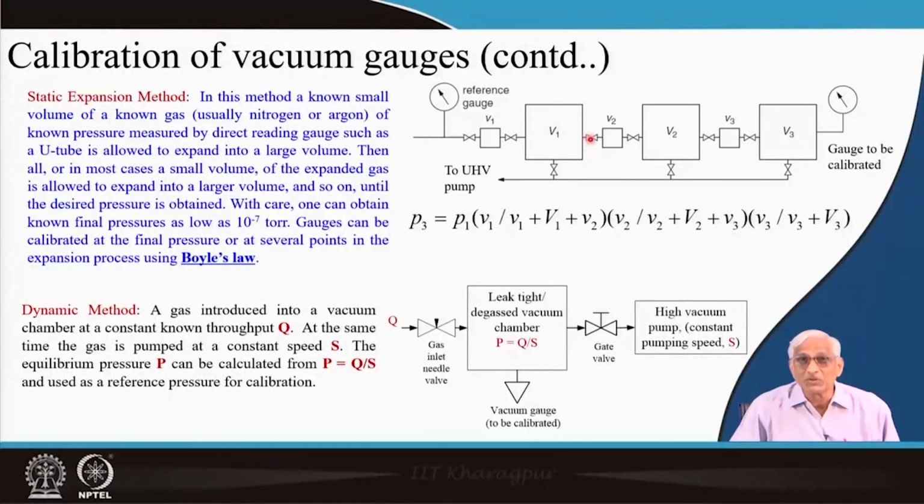And while doing that, you keep this valve open and another small volume, small V2, is also exposed. In fact, that V2 is the pre-volume to the next stage, but we are intentionally evacuating that by closing this valve and opening that valve. That means all three volumes are exposed: small V1, small V2 and big V1.